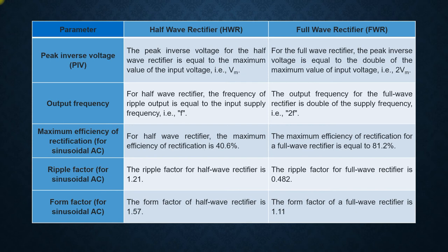As in the half wave rectifier we get a peak inverse voltage of Vm, if we use a bridge rectifier for full wave rectification, we also get Vm only. To make it equal, we go ahead with the bridge rectifier compared to the center tapped rectifier. Otherwise we can simply say the peak inverse voltage is 2 Vm, but in a bridge rectifier two diodes share this 2 Vm.